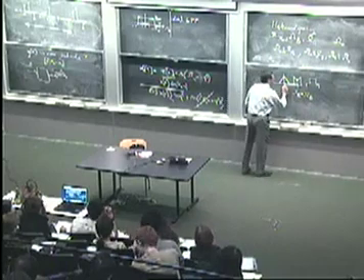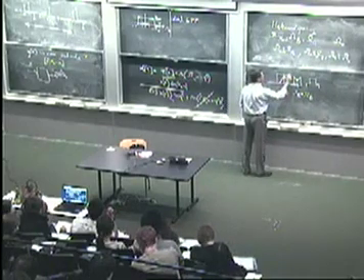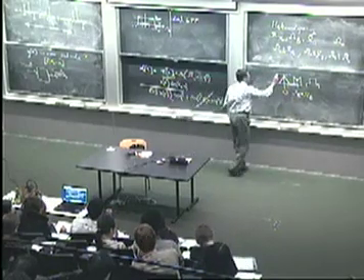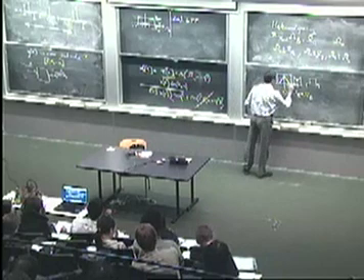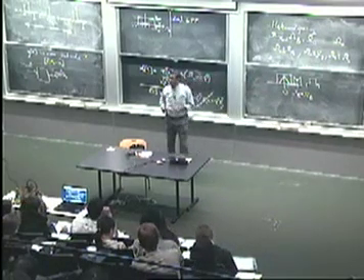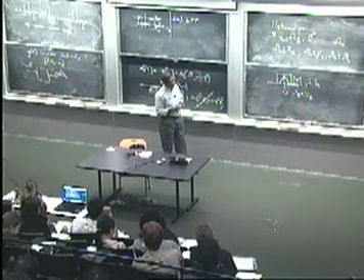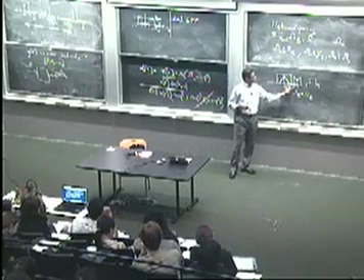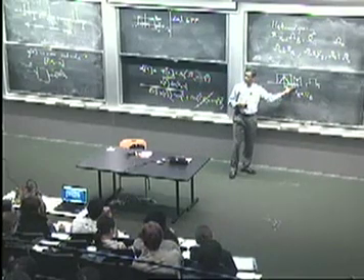So this is at 0, sitting in my low-pass filter, and I want to reject everything else. How should I pick that low-pass filter? Presumably you want the cutoff to lie between these two frequencies.